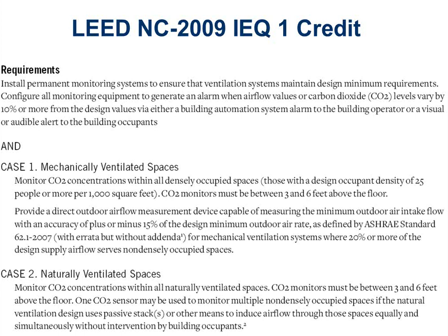At no point in time are we going to bring in more fresh air than the regular code with non-CO2 projects would have had to bring in anyway. So if the regular code said bring in 1,000 CFM for this project, I'm going to modulate it between, say, 300 and 1,000 CFM. I'm not going to go above the 1,000. The old code minimum becomes my new set point maximum.